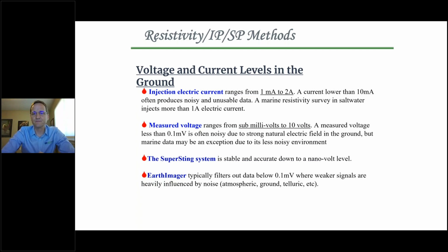Of course, signal to noise ratio is very important. So having your field guys do something as simple as adding a small amount of water and tapping the stake in firmly makes a huge difference, especially in dry desert soils. Raising this injected current up is really good.